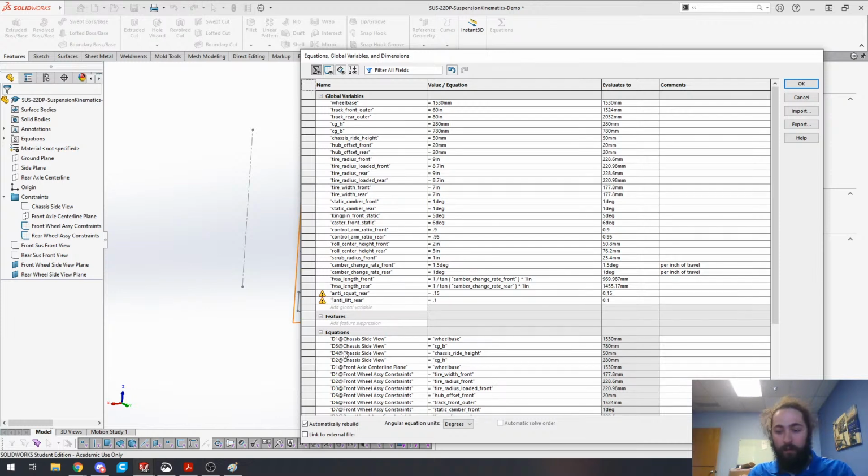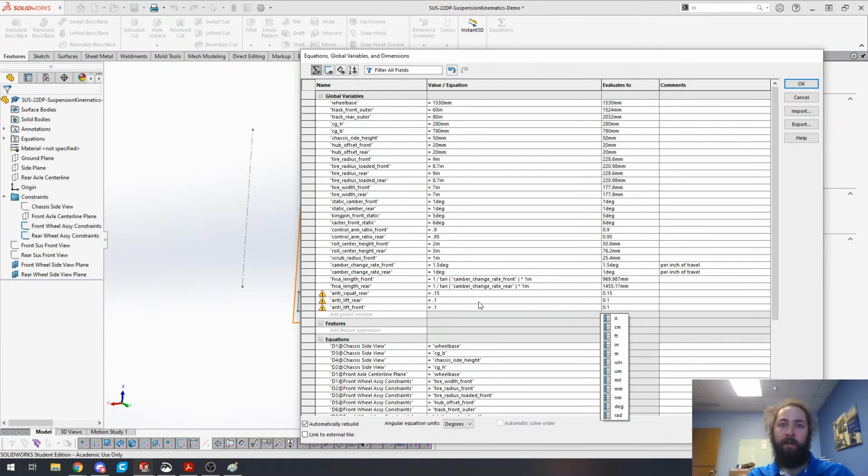I had an extra quotation mark there. And then we'll do anti-lift in the front, kind of same thing I was talking about before. Under acceleration, weight transfer, how much are those front tires going to lift up, and how much is the geometry of the control arms going to prevent that? So here in this case, we're saying 10% of that load, the control arm is going to prevent it. 90% of it is going to go towards upsetting the suspension.